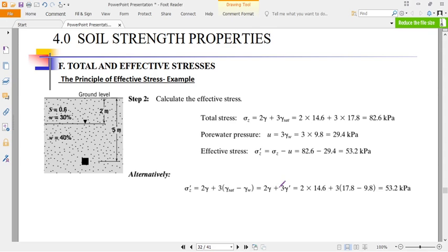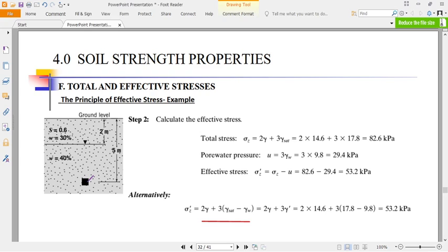Is that okay? Now these are very important parameters. So after determining that, that is one. And then the next one is to determine the stress due to the point loading. We have determined the stress due to the self-weight of the soil. Is that okay? About a point, the effective stress or the overburden pressure due to the self-weight of soil above a point, that point in the soil you are considering. Is it 2 meters, 5 meters, 6 meters? Is that okay? The weight of soil.